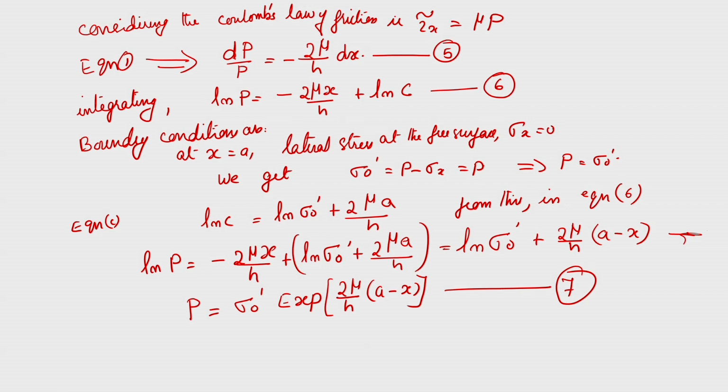Now, this equation we can expand. What is inside the exponential term, we can expand it, because the value of mu is very less. It is always less than 1. Normally, it will be less than 0.5. Sometimes it may vary from a very low value to, normally for deformation conditions, sliding friction, it will come to maximum 0.3 or 0.2. For analysis purpose, you can use any case, but in normal case it is very less.